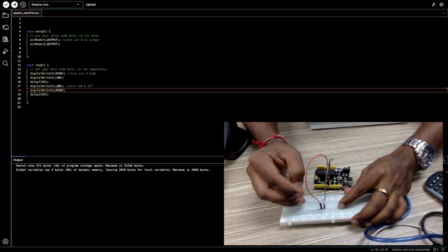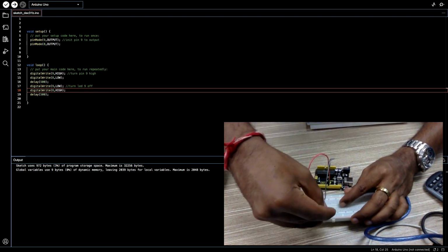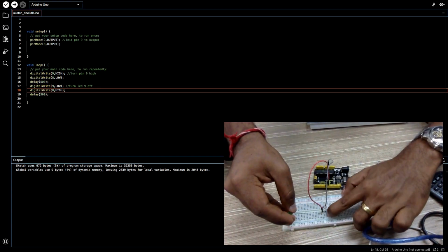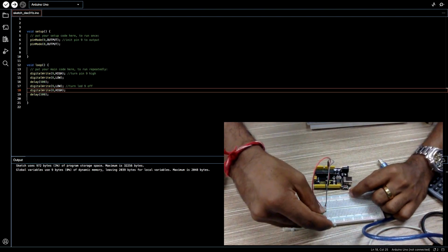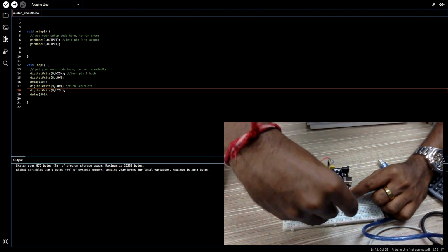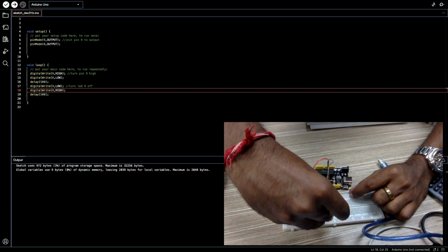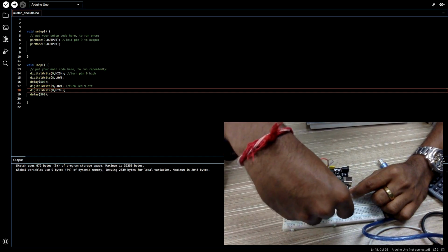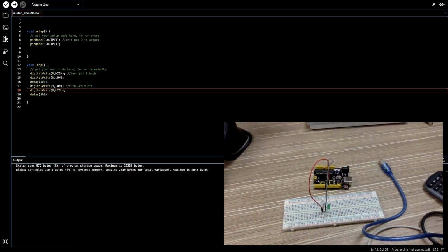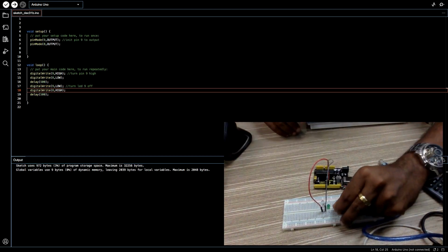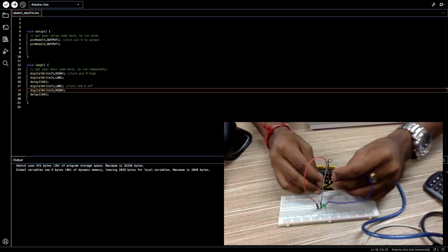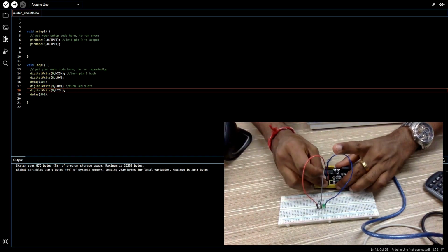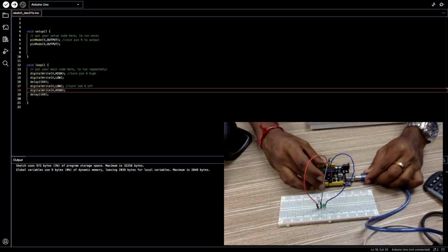In the breadboard, you can see, or you should know, that all of these rows are connected to ground because this is connected to ground. That's how breadboard connections work. So the shorter pin goes to ground, and the longer pin, because we initialized it to pin 8, has to go to pin 8. So in this case, it goes straight to pin 8, and voila.